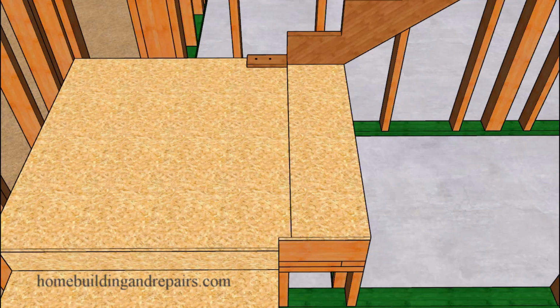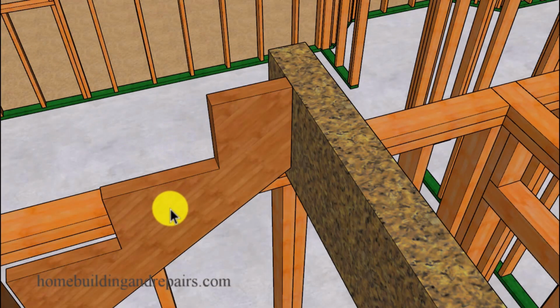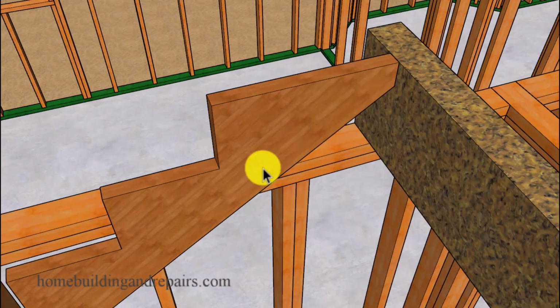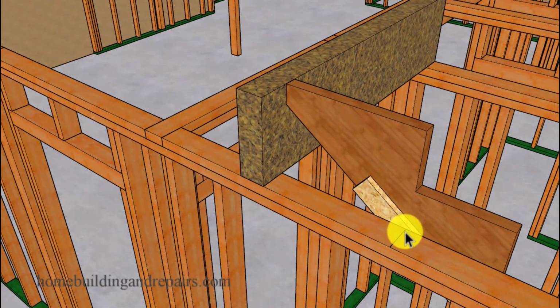And then after we have that, we can just simply cut one stair stringer. And if you have a situation like this, you can pre-cut the stair stringer and then use it to locate the stair headout or support beam. However, if that won't work for you, you can always have the stringer run a little longer and then line it up with the measurement you've selected that will work best for the upper floor framing.